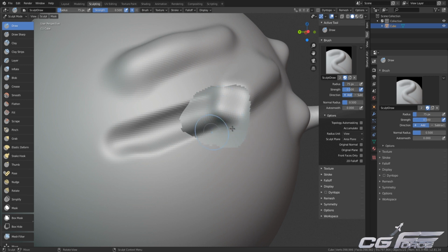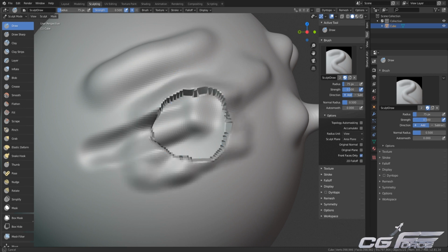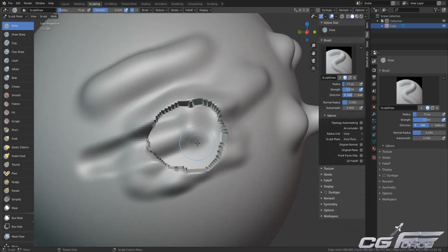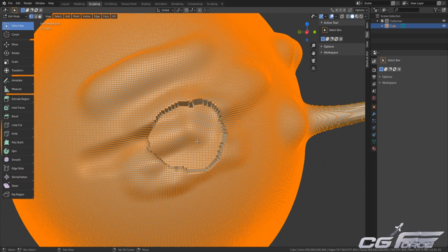Suppose we have these flipped normals which are actually giving us the backside of their polygons or faces. If you only want to work on the front faces, you can simply activate this, and now you can work on this part, and you can see that the back face part is completely neglected by this brush. Now let me change the normals. Select the entire model, recalculate normals by pressing Shift N, and now we are good to go.